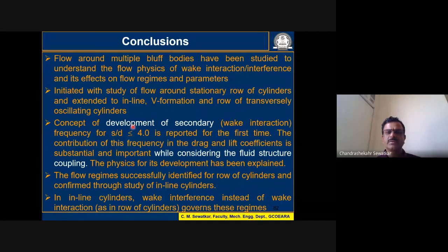The concept of development of secondary frequency, that is the concept of wake interaction, was reported for the first time. The contribution of this frequency in the drag and lift coefficient is substantial and important while considering the fluid structure coupling. The physics of its development has been explained.